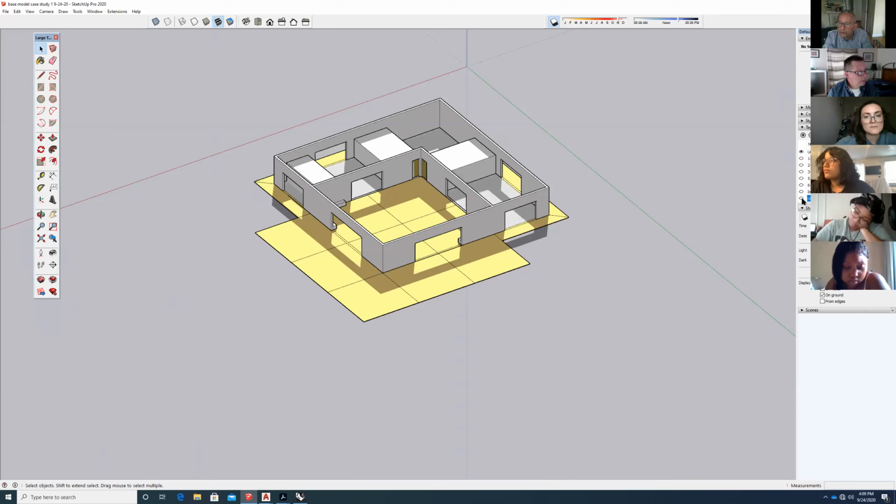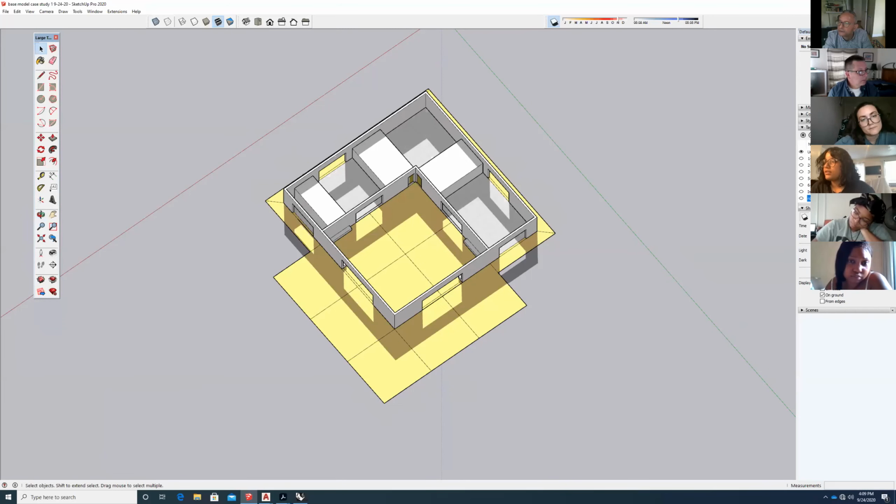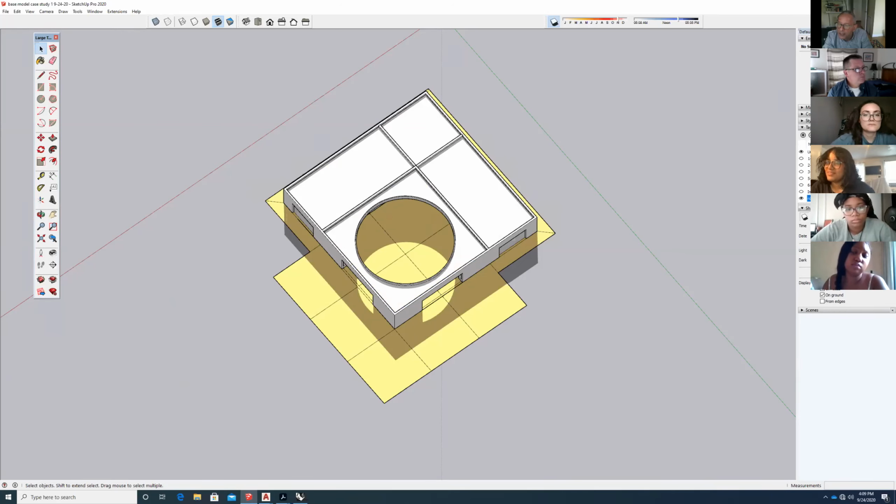So I can control layer visibility. If I want to have an image like this, where I want to see the building without the roof, all I have to do is deactivate the roof layer. There it is. There it isn't. There's also a hide command, but this is a lot more effective. Okay? So this is a lot like layers in AutoCAD. Generally, we'll want the roof on, but there may be times where we want it off or we want to isolate it.